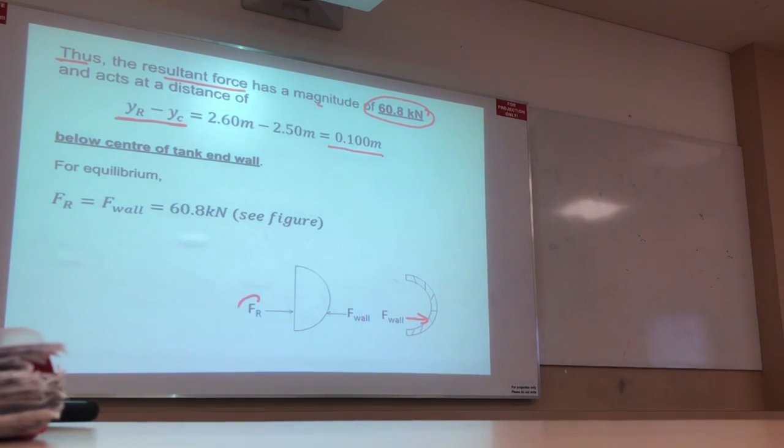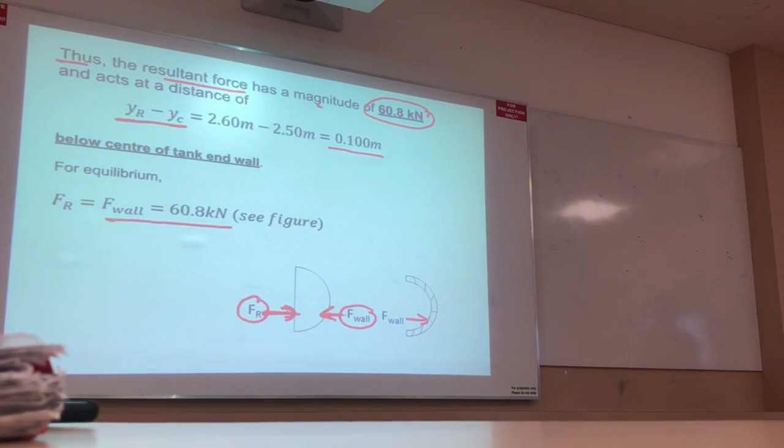They never give you the density, they give you the SG. Because of the force balance, density times gravity, they cancel each other. Divide by 1000, so F1 becomes 60.8 kilonewton. Okay, that's like that. Simple things. It's not new.